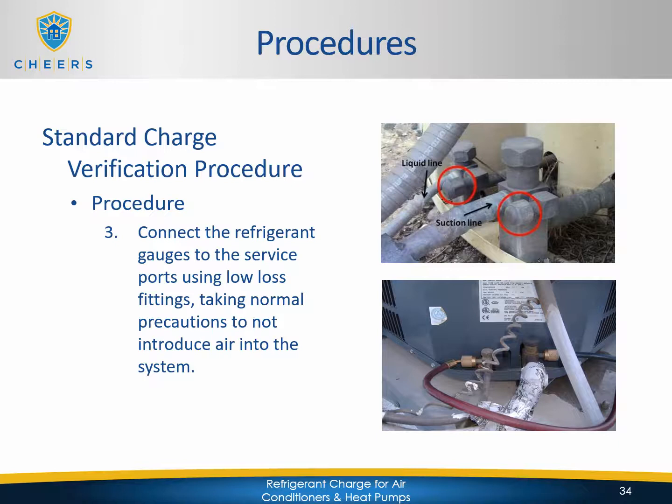You will either need to have the HVAC technician there with you. He can connect your gauges to the system. You cannot use his gauges, you need to use yours. And he can assist you with performing this step and the next steps as well. If you have your EPA 608 certification, then you're good to go. You're going to want to take the hose.